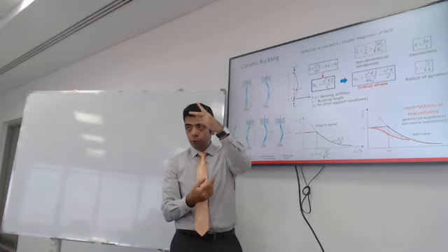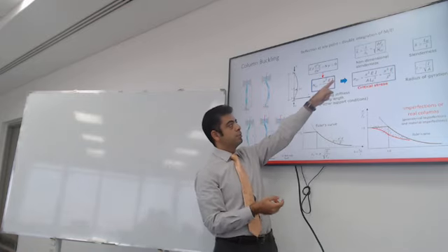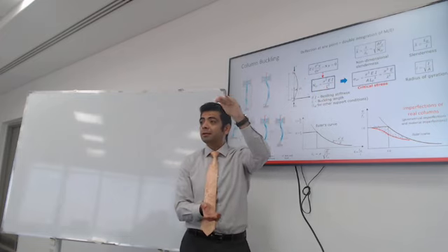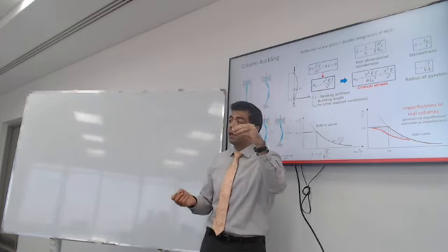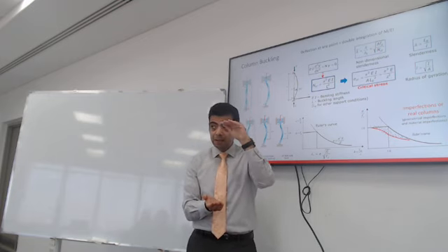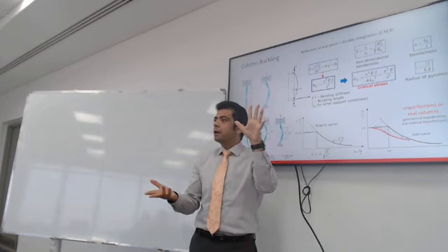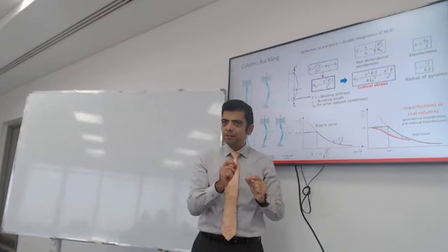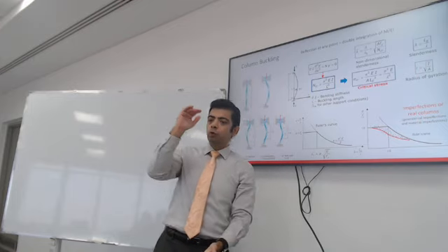You're left with mainly two things: the moment of inertia of the cross section and the length squared. It's not just linear with the length, it's the length squared. So if you increase the length by a little bit, you kind of square the effect of buckling. So columns are very sensitive to their height.